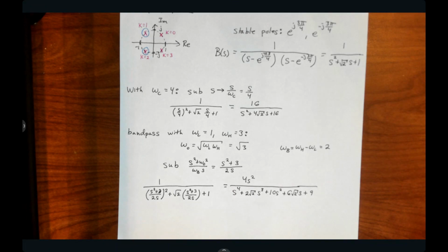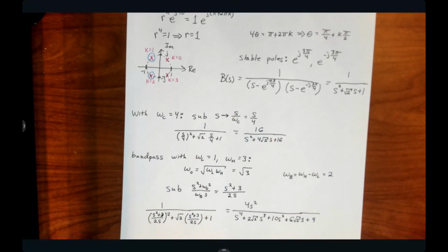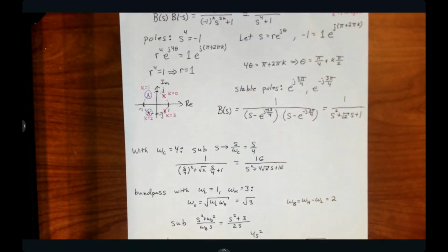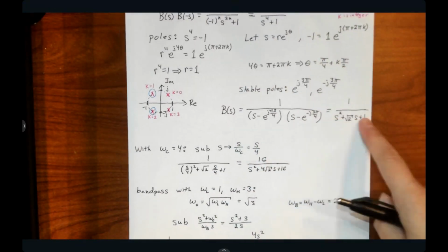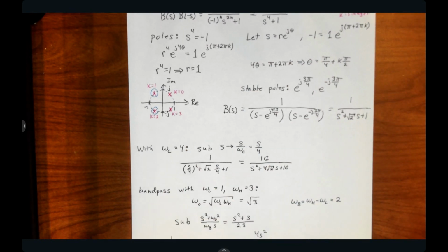And so if you actually look up, say, Butterworth filter on something like Wikipedia, what you would see is for different filter orders, what these coefficients are that you would expect to see in the transfer function. And so from here, you can see where those are actually coming from, what that form is that gets us to these coefficients. Really, it comes down to making sure that we have stable poles that give us an approximation of the ideal low pass filter that we want.